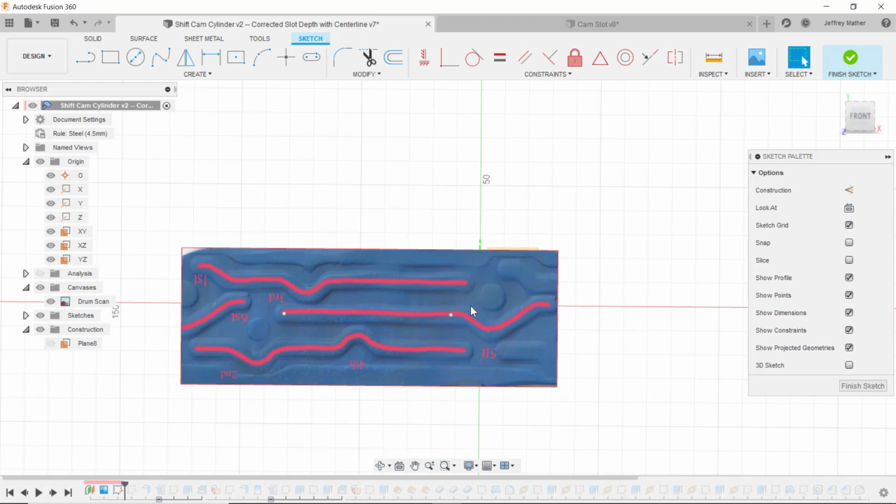You could dimension these lines to get our displacement diagram, but don't take the image too seriously. Hopefully you have a physical part that you can go back and forth with, between your measurements of the physical part and the image, because it's hard to tell from an image. You're always going to have parallax error, some errors that make it difficult to use the image. Anyway, I went through that process and created a displacement diagram.